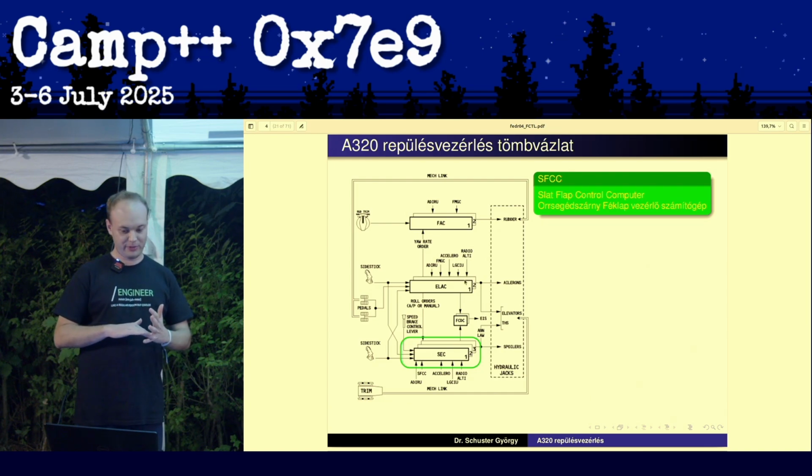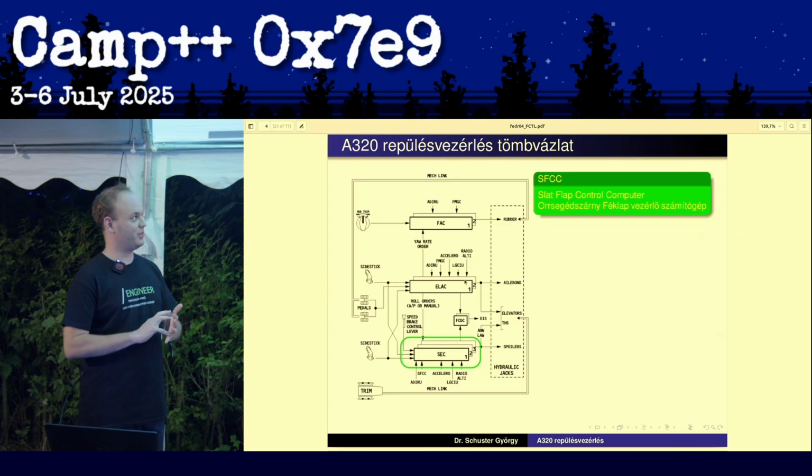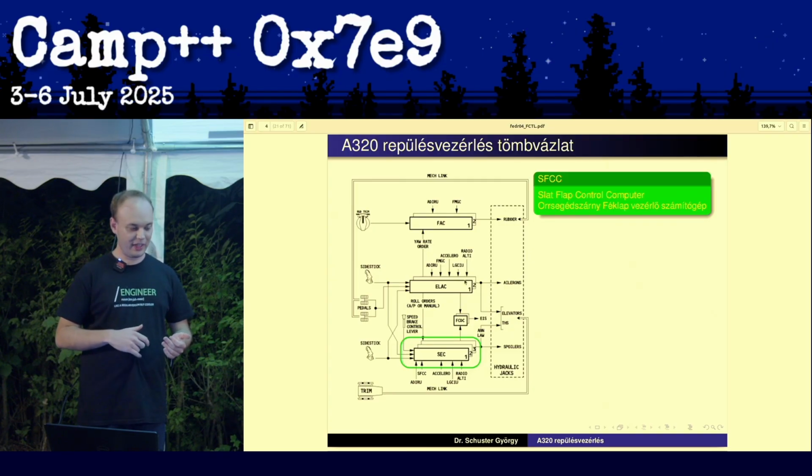The maximum deflection of the stabilizers is, I don't know the exact value on the 737, but it's somewhere between 5 to 10 degrees. There are these trim wheels that are normally driven by motors, and there are electric motors that turn the actual trim wheels in the cockpit. And they are all either controlled automatically or with a little switch on the yoke.